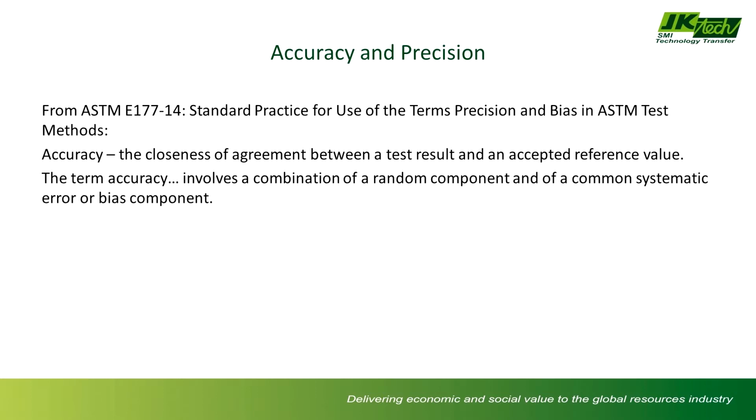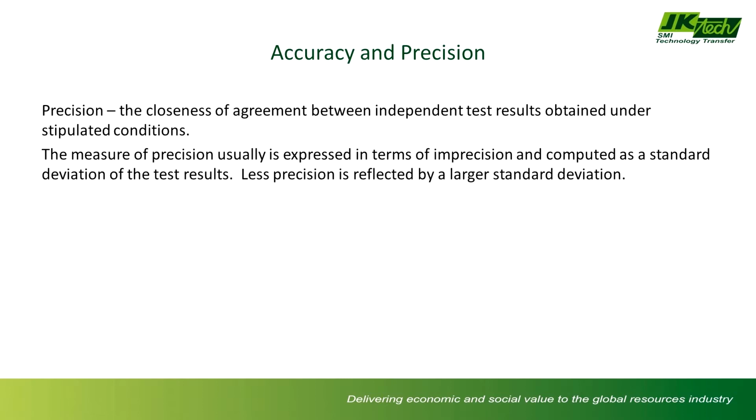Closely associated with that is precision. I believe a lot of people regard precision basically as how many decimal places do I have in my measurement. That is part of precision, but it's not the whole picture. Technically, precision is looking at if you do a number of measurements on a sample, how close together are those measurements? That's when you're really looking at the variability in your measurement or your test method. There are a number of ways to characterize this. Standard deviation is obviously the obvious one.